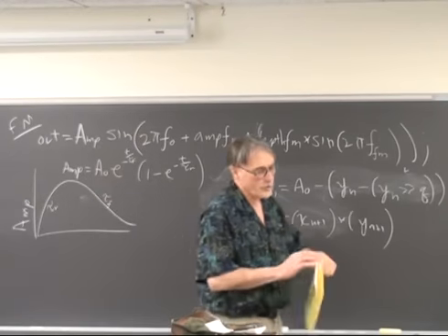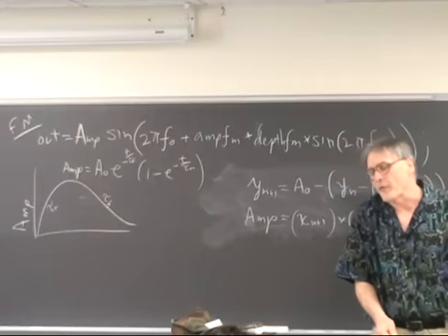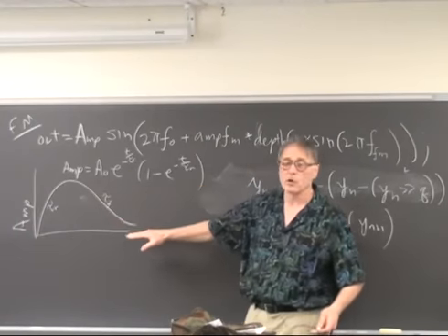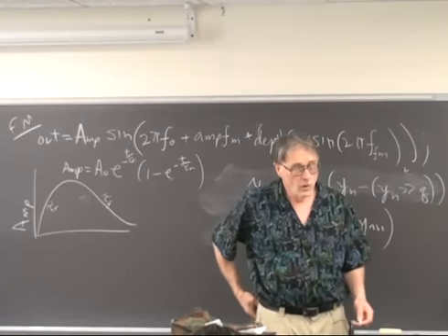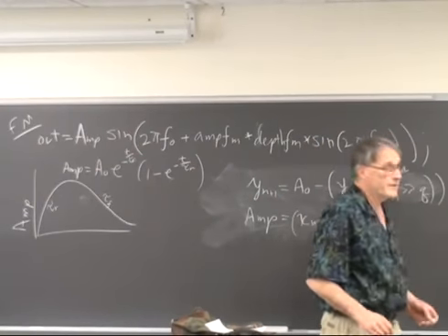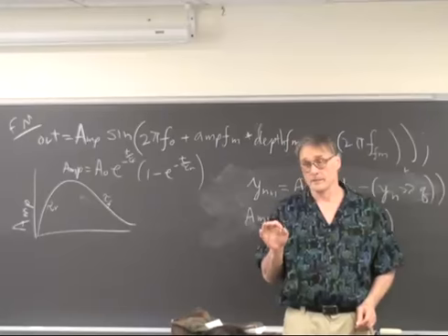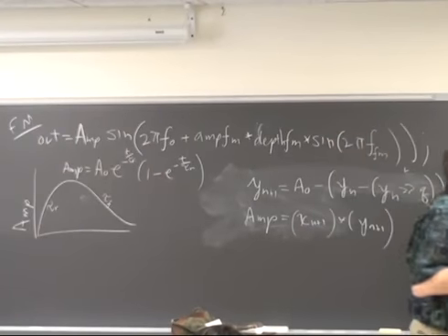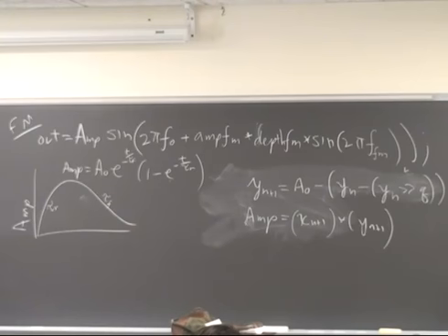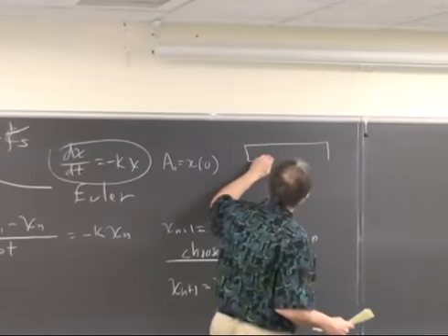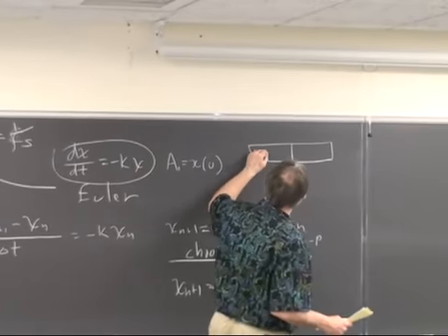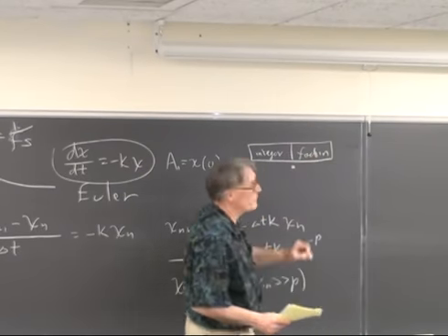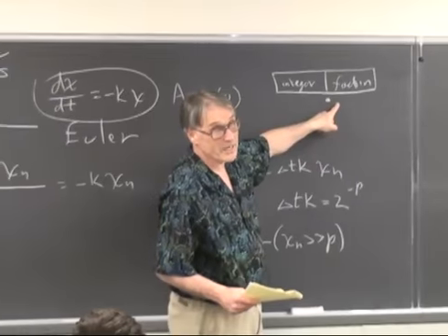So we're going to use integer arithmetic, but we really need fractions because we want these functions to change smoothly and slowly. So what we're going to do is say that a 16-bit int, in our heads, we're going to pretend is really an integer piece and a fraction piece with a binary point between bits 7 and 8.